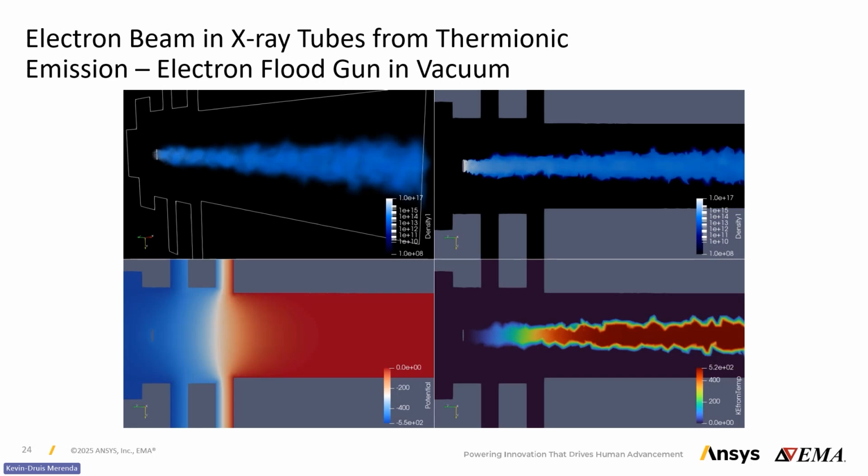You can run the PIC without electrons, or without ions, or without neutral gases, just with electrons, or even just with ions if you wanted. You can also run it just with neutrals. And if you want to model a rarefied neutral gas moving around in a chamber, you can do that as well, right? That's what the PIC solver is for. In our case here, it is coupled to the electromagnetic solver, and you effectively want to model the proper space charge contribution for each of the charge species. This is what we can do here with the tool.